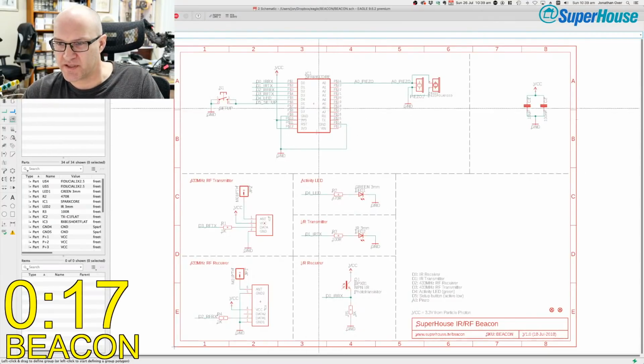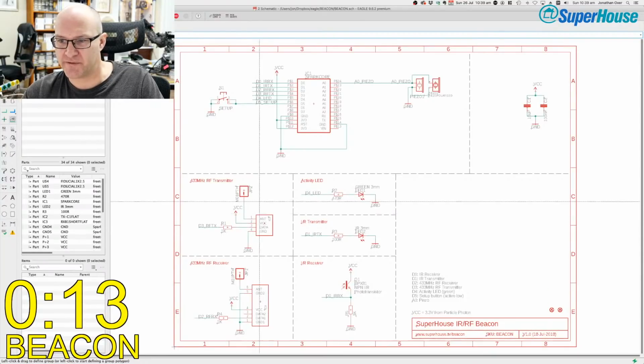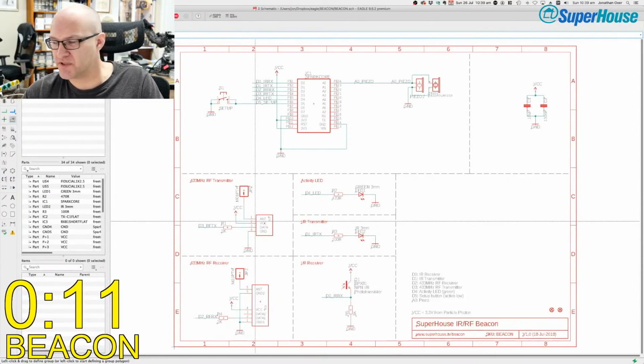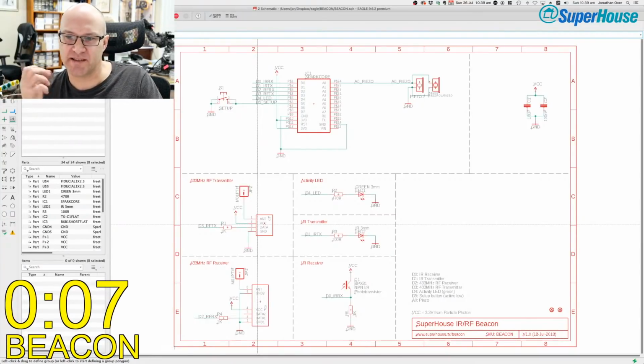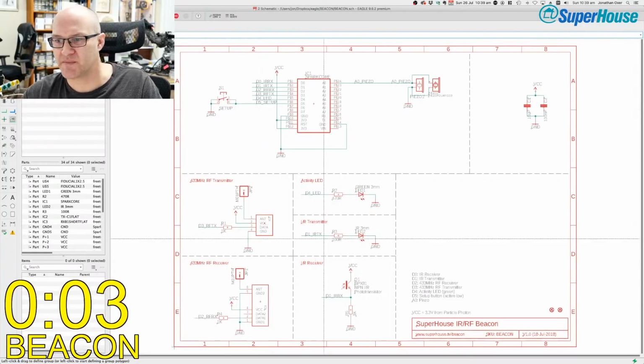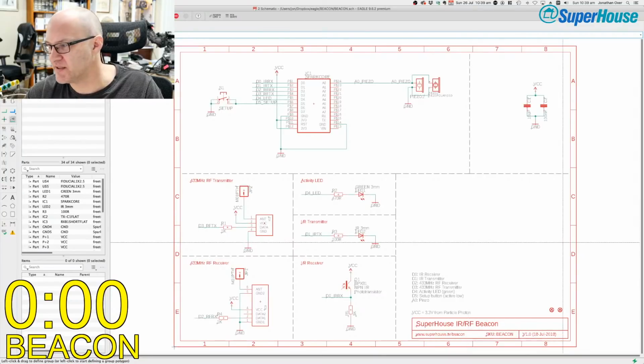And what it does is expose transmit and receive for infrared, and transmit and receive for 433 megahertz, so that you can do an IR blaster, and you can also do an RF blaster, and you can decode signals from transmitters as well and link it to MQTT.